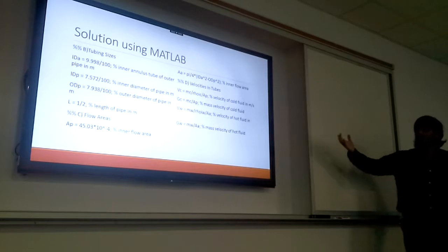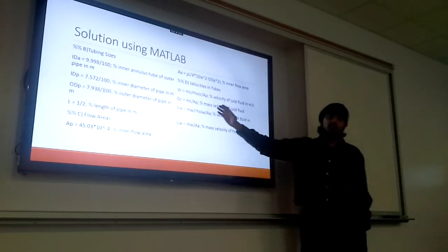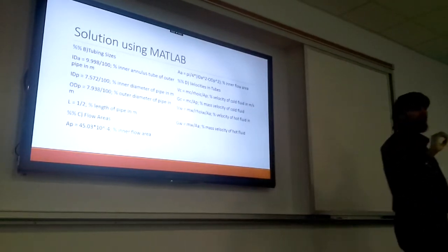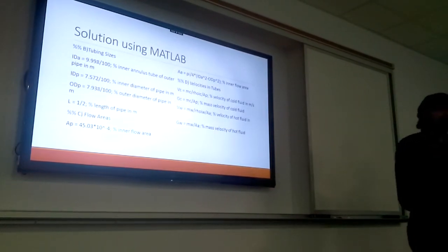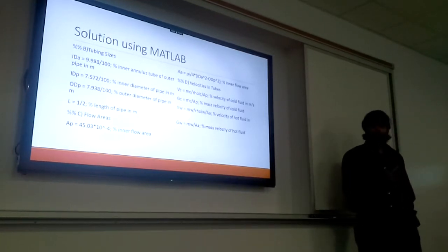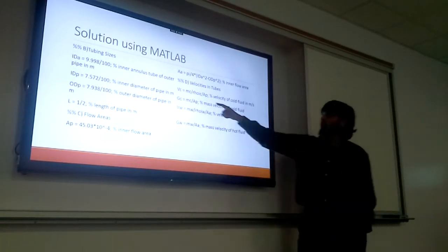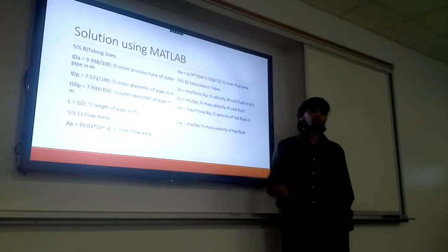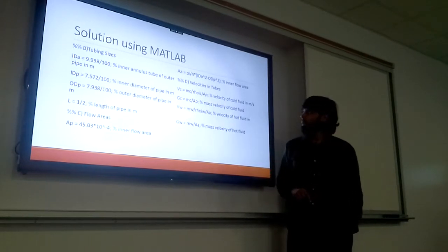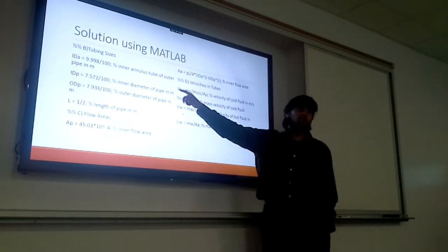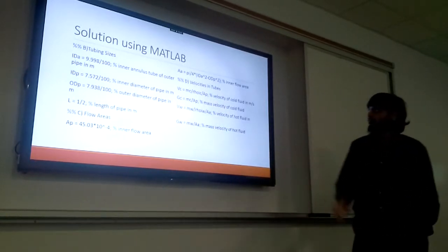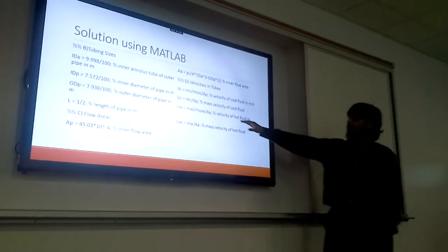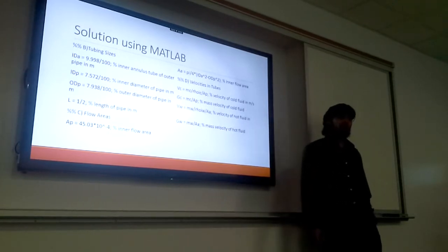Once you find the tubing sizes, you can find the velocities, because we already know the mass flow rate and the density of both fluids. When you apply the areas, you can find the velocities for both of those. VC means the cold fluid and VW means the warm or hot fluid, however you define it. We can also find the mass velocity of those fluids.